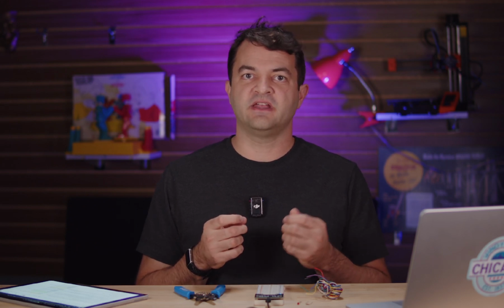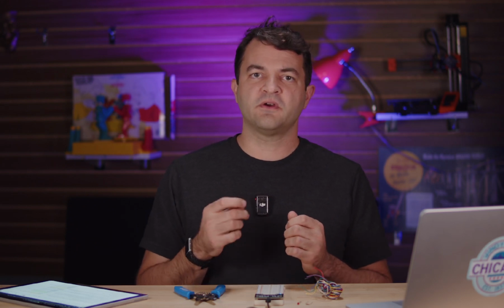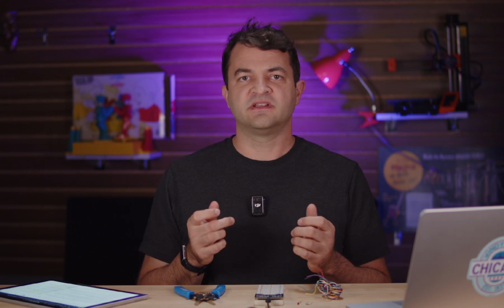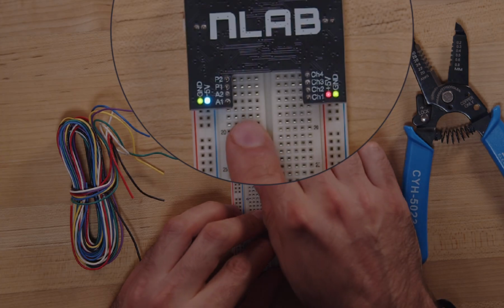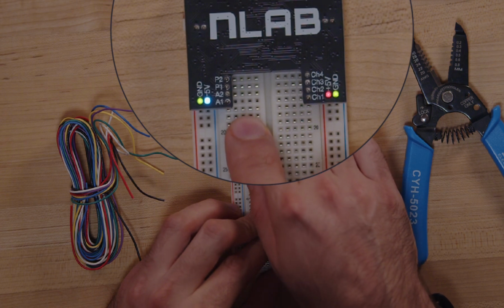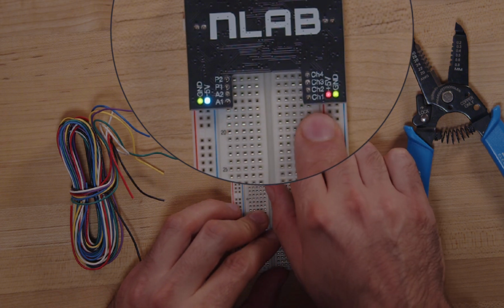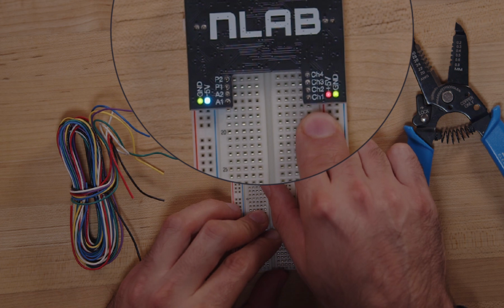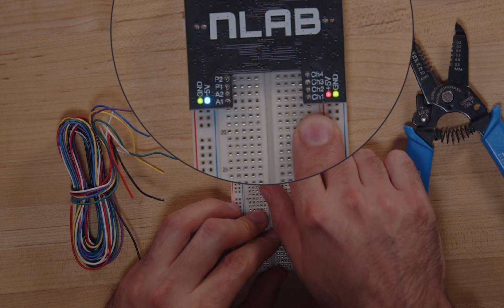In this activity, we're going to use our signal generator to make a signal that goes into our LED. We'll change the properties of the signal so that the LED blinks, and then we'll view it with our oscilloscope to verify that it blinks the way we expect. These pins on the left, A1, A2, P1, and P2, those are the signal generator pins. The pins on the right, CH1, CH2, CH3, CH4, those are our input channels to the oscilloscope.